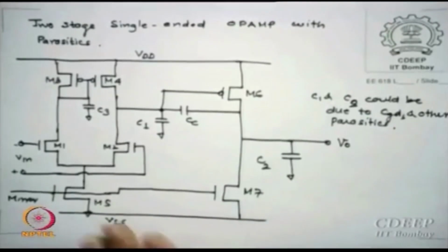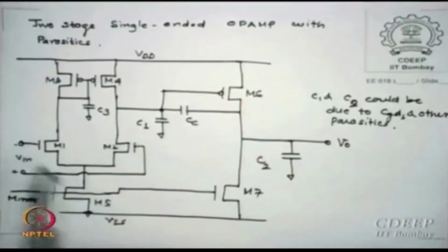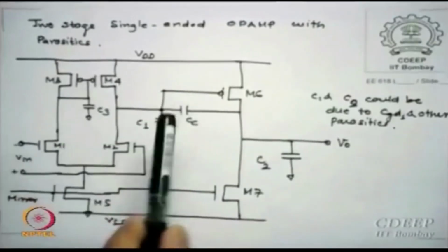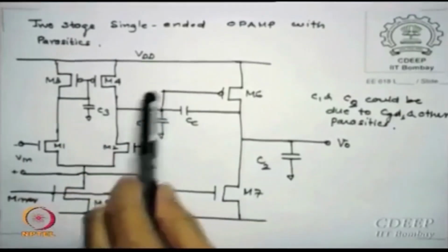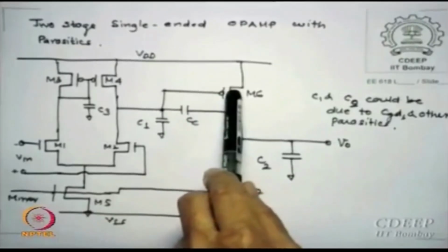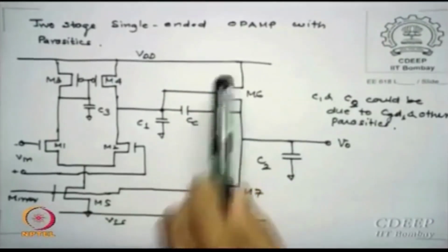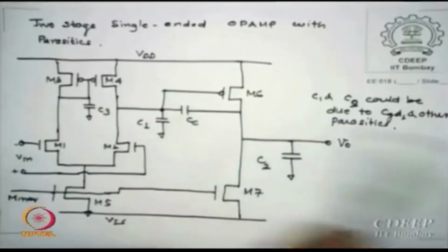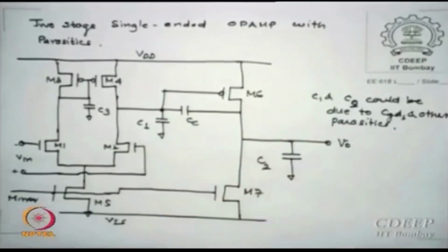I also should see that C3 and RC3 are not very important, and then I move ahead. Now this is a differential amplifier whose output, which is single ended because of the diode connected loads, is fed to the P channel driver, which is M6. Right now you may forget CC, or you can put dotted lines on it if you wish.